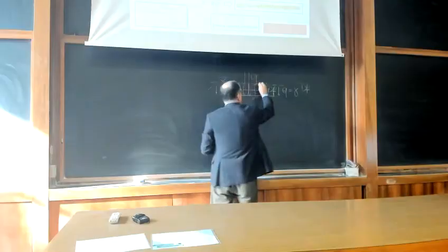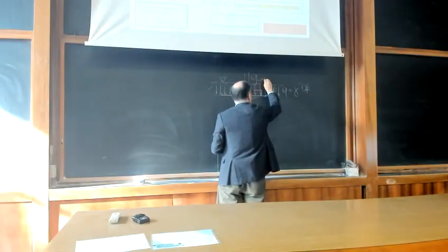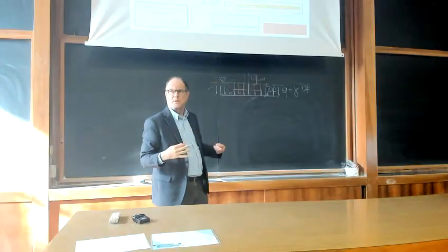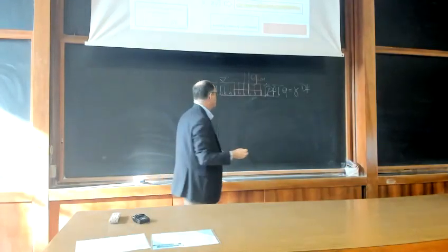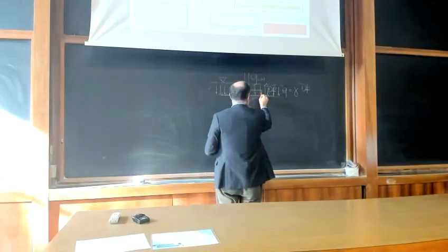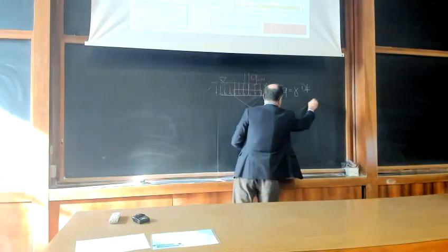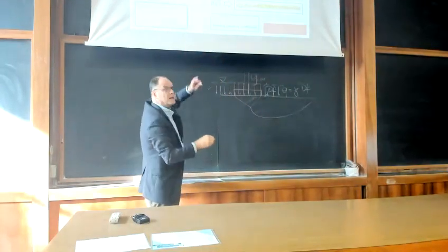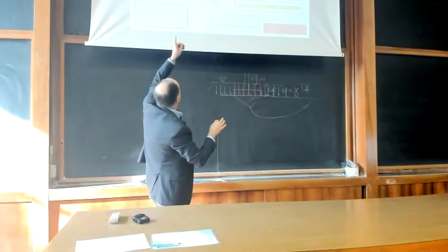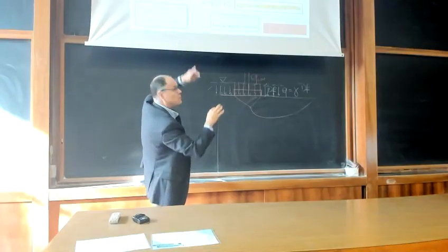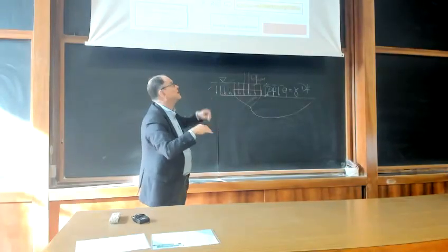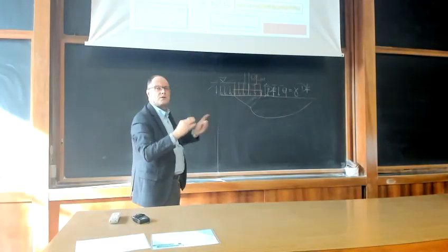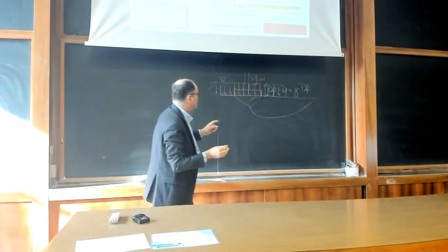So we are looking for the limit load at which we develop a full general mechanism into the soil, which is something like that, as we have seen before. And we can build a proper mechanism, like the one in which you define all your curves, you have an analytic expression of your curves, you equalize the internal work and the external work, and you end up with your Q limit.